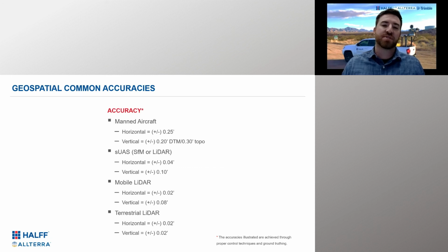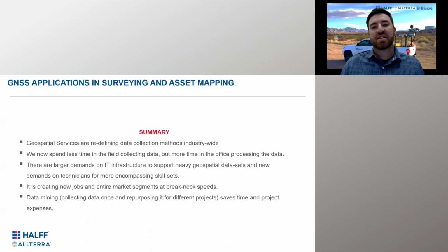from our systems. Obviously, the terrestrial LiDAR, because there's no motion involved, is the tool that we push out there if we're doing a structural analysis. But generally speaking, with our mobile system, we're getting 5 millimeters. We're getting excellent data sets if we use proper survey control and tie it properly.